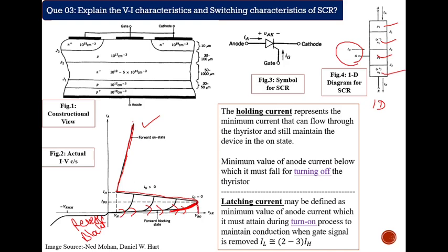So this is called the breakover voltage. When Ig equals 0, what is the maximum voltage we will achieve? This is called the breakover voltage, which is not desirable. But if you are increasing the Ig from 0, let's say to this one, then this breakover voltage is decreasing, which is very good for us, because the manufacturer provides a limit breakover voltage, let's say 1 kilovolt.